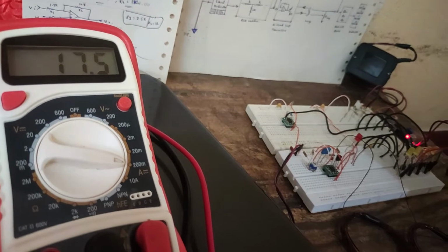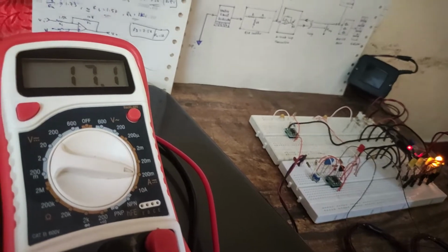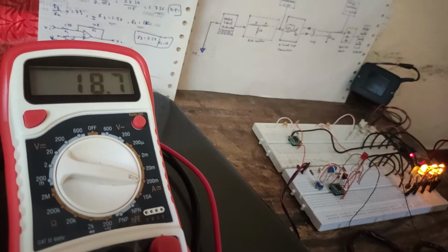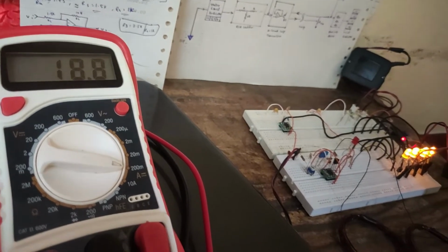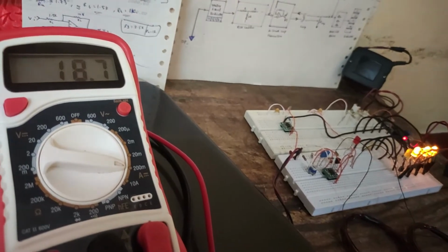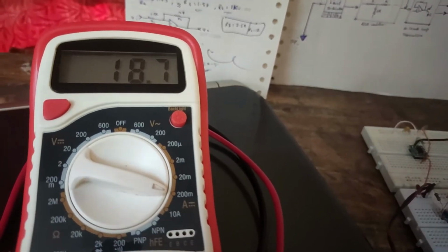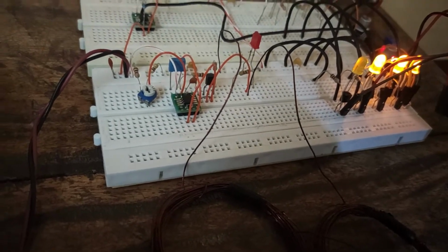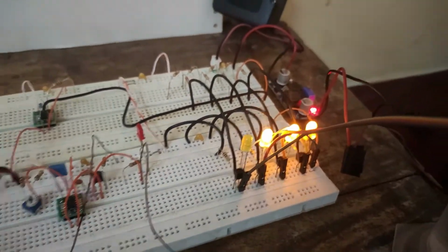So overall, with the current difference of 17.5 milliampere to 18.7 milliampere, or now 18.8 milliampere, all the values of these are encoded. So this rightly lies in the range of 0 to 20 milliampere. But of course we are not using the full range just because the conditioning circuit is not the standard one, and I'm using a power supply which is not 24 volt.